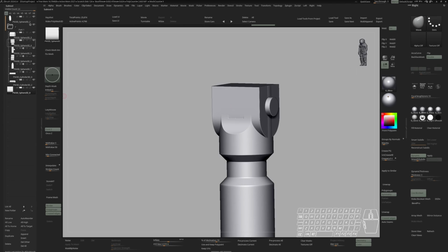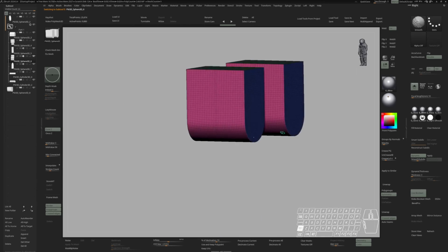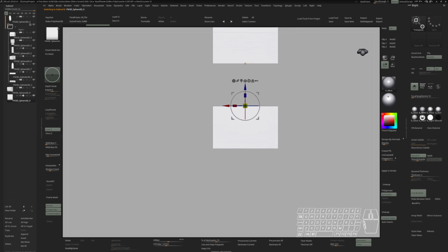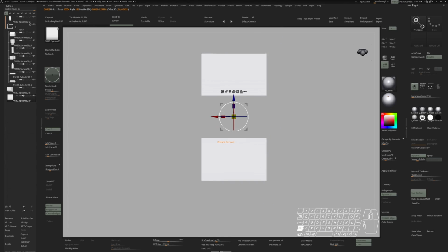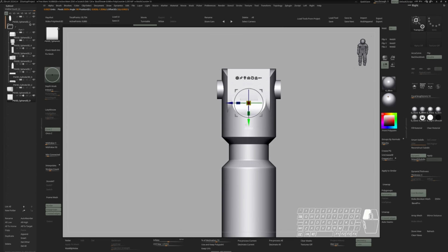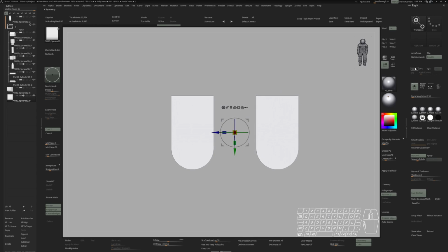And let's also grab those two, duplicate them, and move it underneath this new piece. Activate subtraction. Turn off symmetry for now. Let's center our gizmo and rotate that by 90 degrees in the vert axis. Let's move them down, activate X symmetry. Let's do a weld, mirror and weld in the X as well to recenter everything.